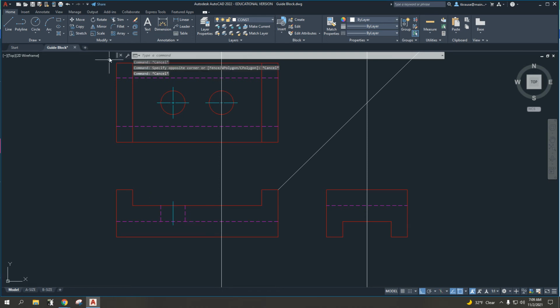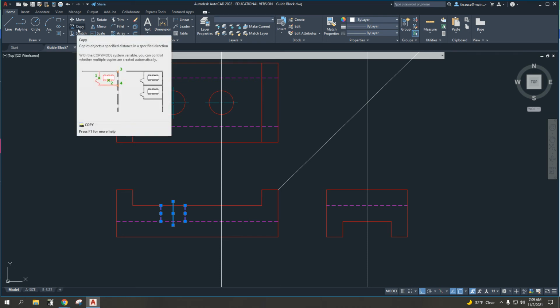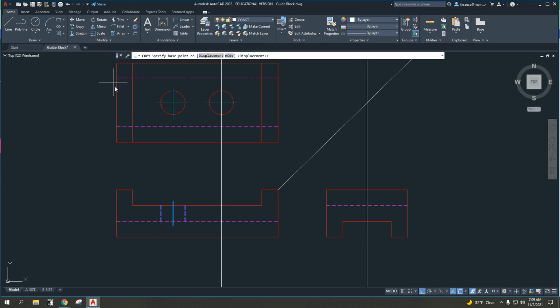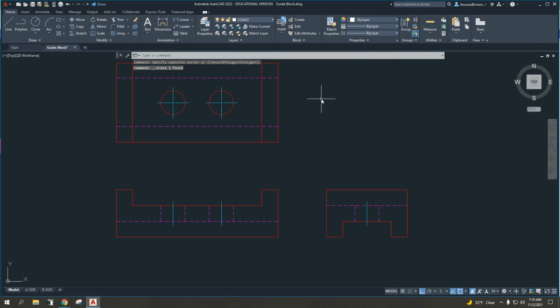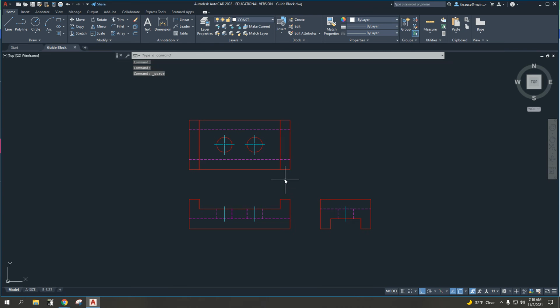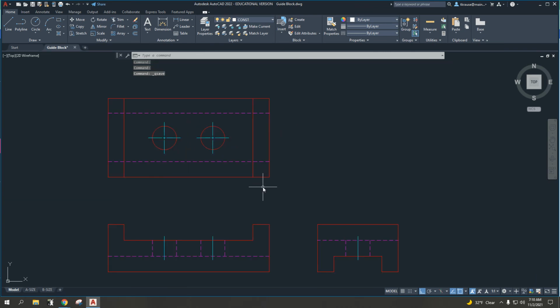One circle. So what I'm going to do now is I'm going to select with a window, okay? This is a from the left to right selection window. I'm going to select this information for that circle, and I'm going to copy it. Okay, I don't think we've done too much copying, a little bit on circles and whatnot, but now it's a hidden circle. So I'm going to copy information from, let's say, this top intersection point, and I'm going to copy it right to here, right? That's from the center of this circle down, and since the circles are the same size, I can place that one there, and I can do the same thing over here. Hit escape, delete my projection lines, and I effectively have the geometry for this object done, okay?